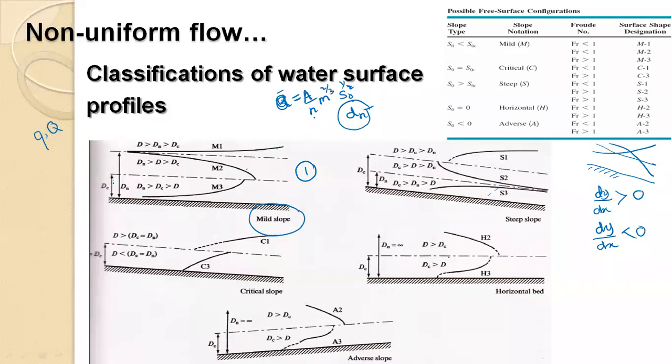Now, in this case, you will clearly see that the virtual quantity critical depth is less than the normal water depth, right? When you have something like this, there are three regimes. I'll take this one as 1, I'll have 2, and I'll have 3. So there are 3 regimes where the water profile can take. The first one is denoted by M1 profile. We call it M1 profile.